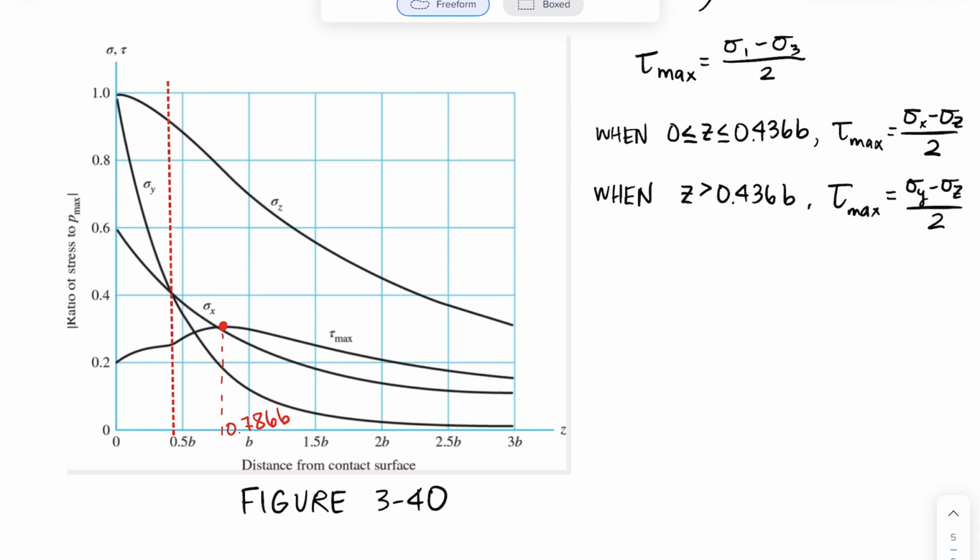For rolling element bearings, we will, in this section of the class, tend to assume that we are not applying shear with friction. So that means we're assuming that we have really well lubricated gears, or really well lubricated rollers. But for more accurate models, you would want to include a shear component due to friction.